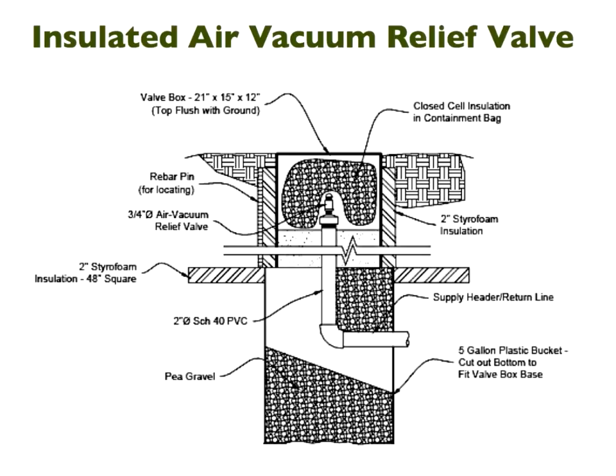There's water being pushed up here, and it's wet, and it can freeze. It's one of the most likely areas to freeze. So this needs to be insulated. Here we have a bag with closed cell insulation material in it, wrapped around.